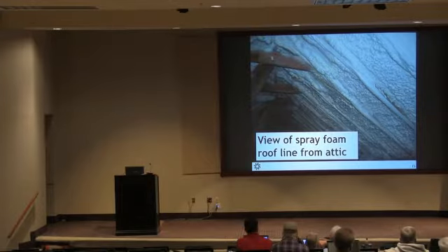But the reality of it is, yes, you may have to cover this for combustion, for fire safety, and that depends on the type of foam you spray and that particular manufacturer's spec. It's more likely that you're going to have to do something with an open cell foam than with a closed cell foam. But you really have to go look manufacturer to manufacturer and see what their foam is rated for.